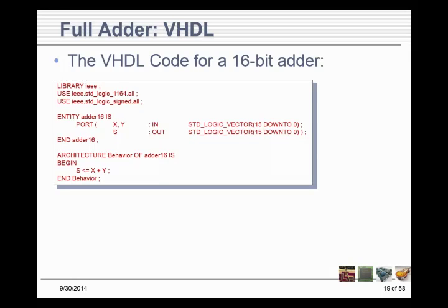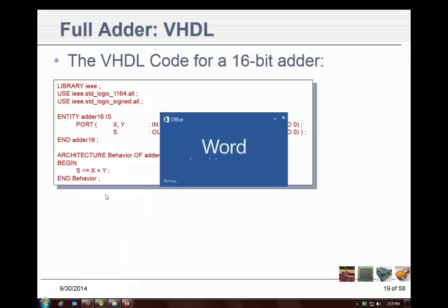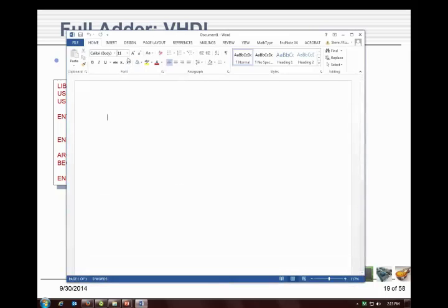I hate this, but I can't go to the board, but I can call up Microsoft Word. So I want to ask you something about this number I'm about to type in. Let's get some big numbers up here. Okay, is that number in decimal? That's a binary number. Is that number 10 or is that number 5? How do you know? Is this the most significant bit? If it's positive logic, it's 10. If it's negative logic, it's 5, right?